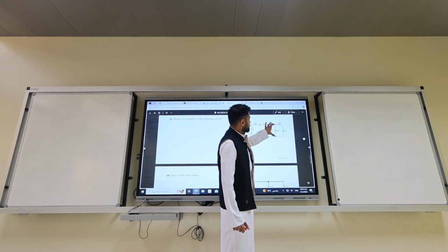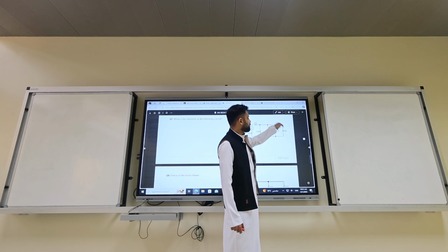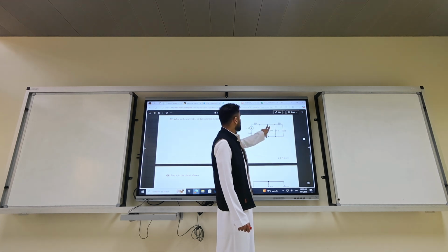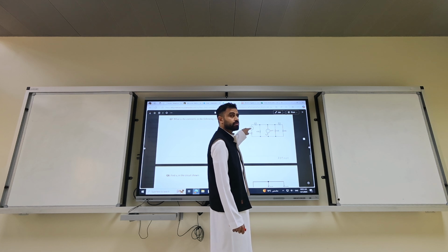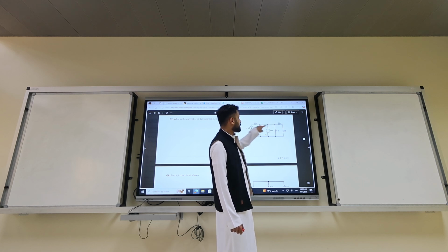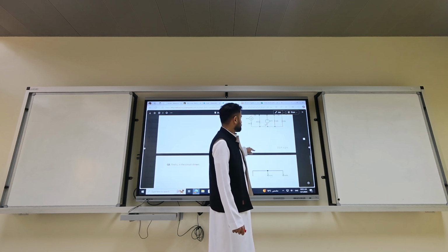The voltage here is parallel here, so you combine those two resistances. We'll study that today. This is 12. 14 over 12, you can calculate the current here. This 14 over 4, you can calculate the current here. You already know the current here. So you do KCL around this big node, and then you can calculate I0. Get it?